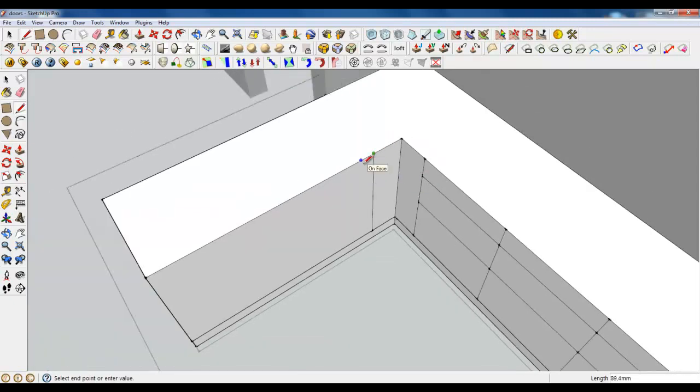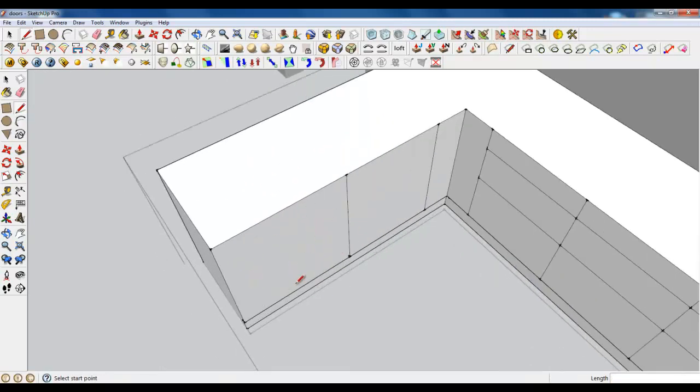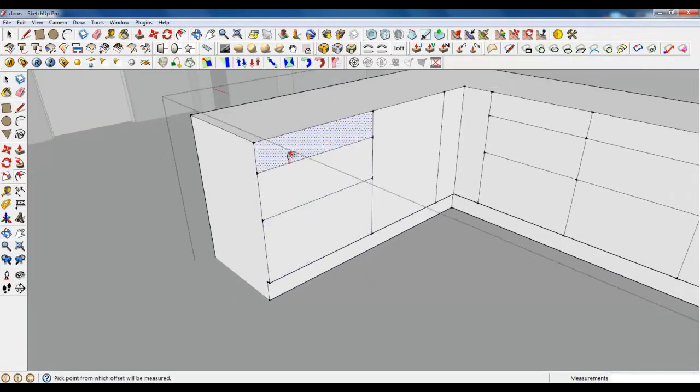Okay, so 600 for the cooker or oven, and leave everything for drawers. So it's 142. Let's type 142 and 359. Perfect. Now we're going to use the offset tool. So select and type in 1 and do the same things except the oven, please.